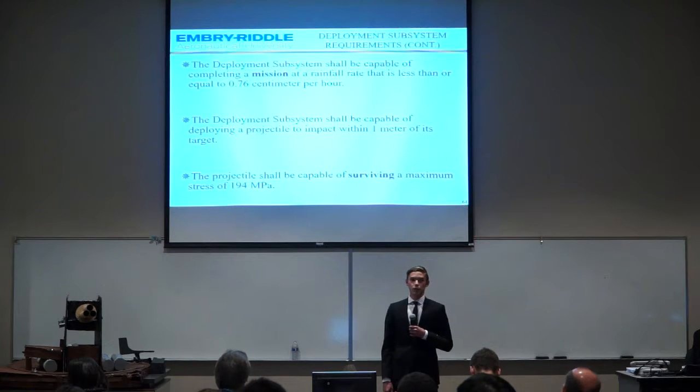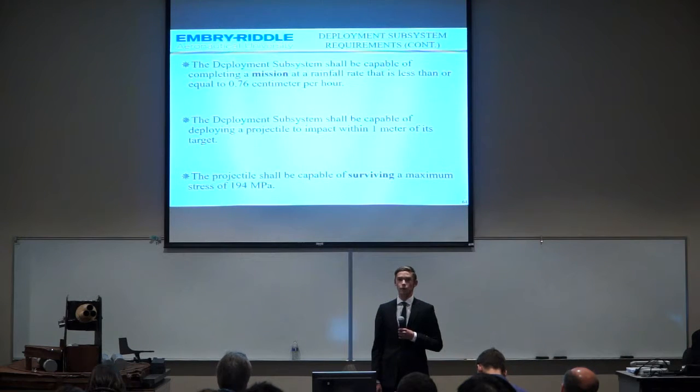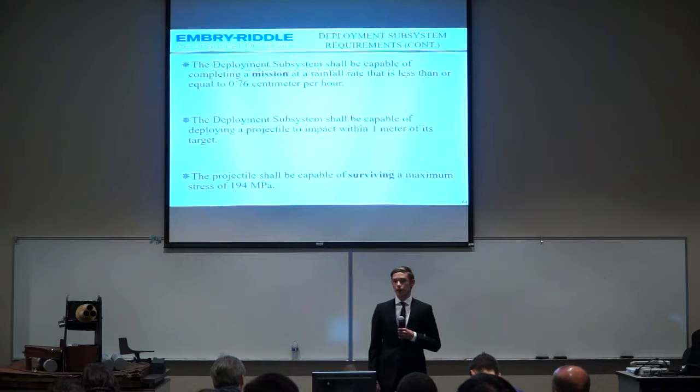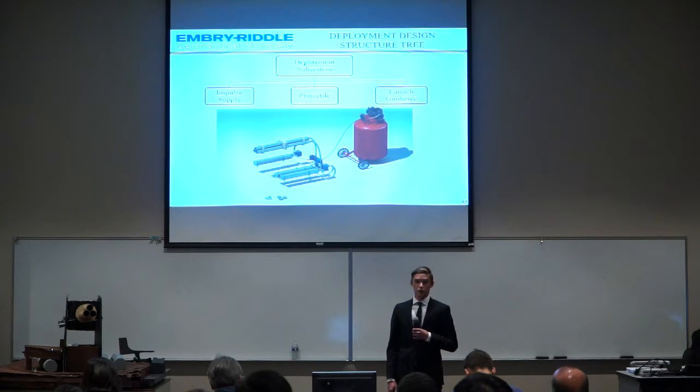It should also be capable of completing a mission in rainfall rate less than 0.76 centimeter per hour. The subsystem shall also be capable of deploying a projectile to impact the target within 1 meter of itself. And finally, the projectile shall be capable of surviving a maximum impact stress of 194 megapascals. So on to the deployment subsystem structural tree.